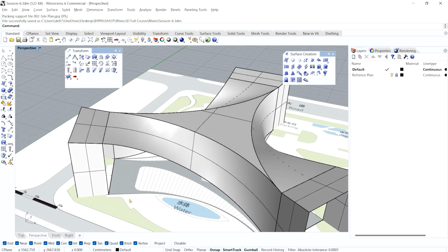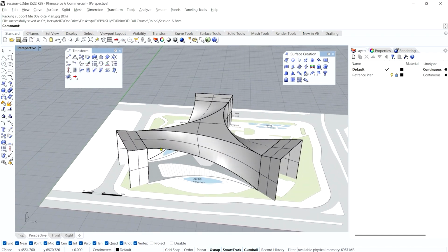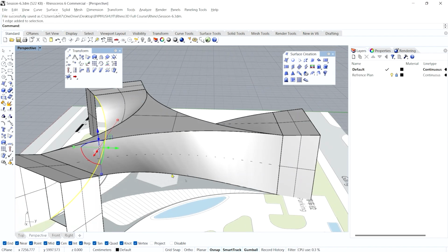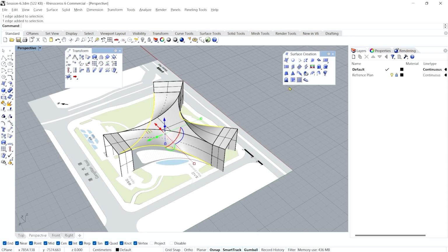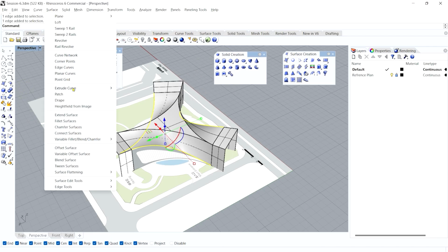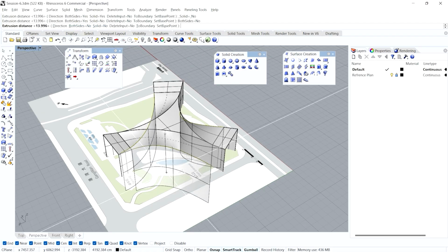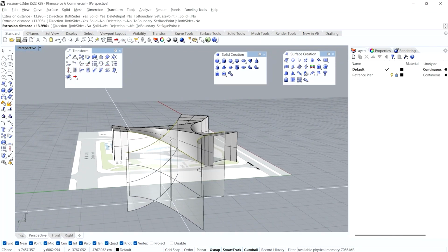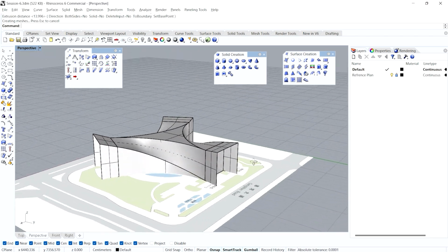Next, we need to fill up these vacant surfaces. So these are like fully extruded lines. What we will do is again select these lines, Control Shift, right, and this one, and then again go for Extrude Surface. From the solid tools you can bring it, or you can go to the surface and Extrude Curve Straight. It is going both sides. If you see in the command line, it says both side yes. You can turn it off and just pull it down, it doesn't matter. Later on I will trim it with the planar surface. Now you can see this thing is also done.